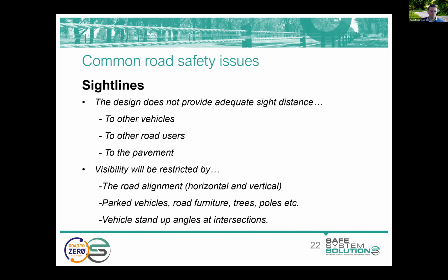If we're talking to sight distance to the pavement, we're talking probably about approach sight distance, which is measured between the driver eye height and the pavement level to allow motorists to see pavement markings in particular.